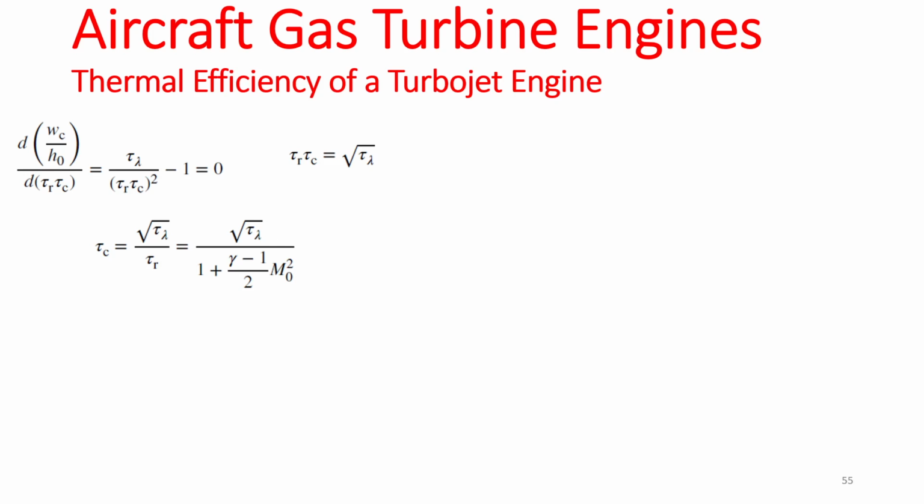So how can we relate tau c to pi c, the pressure ratio? We already have that relationship, don't we? So go back to your notes, and find the relationship between the pressure ratio of a compressor and the temperature ratio of a compressor.